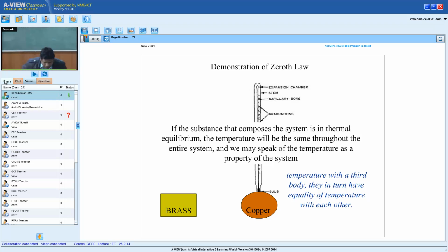The second one is the time constant you have mentioned, is it only valid for a particle? No. See, the expression for the time constant which I have given is valid for any thermometer, but you need to know the corresponding density, corresponding volume, corresponding specific heat, and corresponding heat transfer coefficient. Otherwise, for any kind of temperature measurement, this is how the time constant will be decided. You only need to measure rho, V and C appropriately. That's all. Otherwise, it is reasonably generalized, unless the system is higher order, which I'm avoiding for the time being.